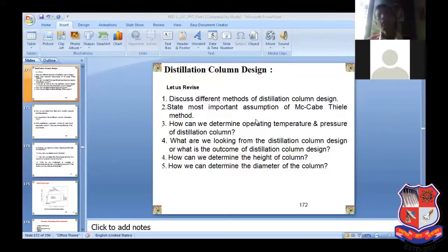So how can I increase the boiling points of nitrogen and oxygen? It is easy: let me increase the pressure. If I increase the pressure from 1 atmosphere to maybe 50 bar or 100 bar, you can check how the boiling point changes. That's how we choose to separate nitrogen and oxygen from air at a higher pressure, where a low temperature comes into the picture as well.